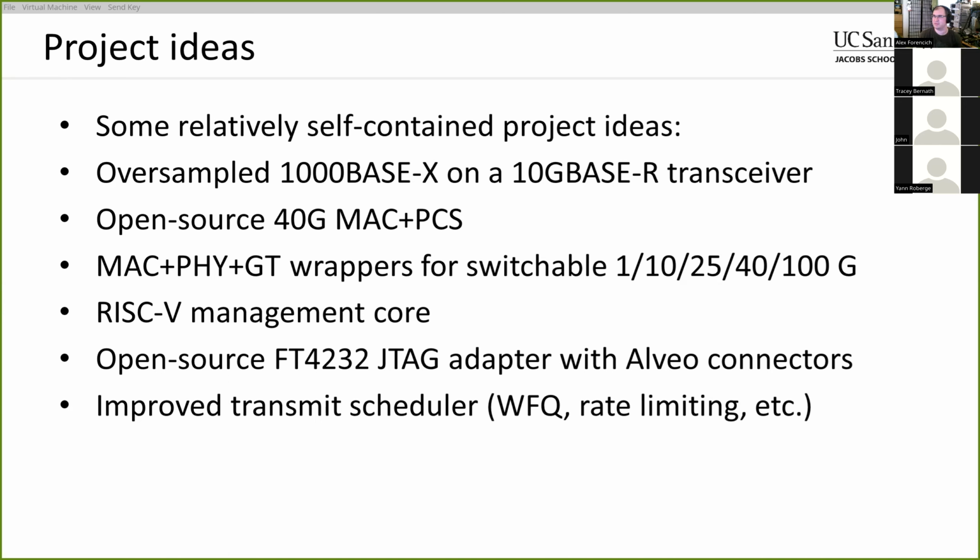Although I guess what you can always do is potentially have two copies of the firmware. One of them built into the bit stream and preloaded into internal block RAM, and then another copy of the firmware in flash, and basically a bootloader that checks to see if it's there in flash. If it is, then it'll load that one. Otherwise, it'll run with whatever's been preloaded into the block RAM. That might end up being the most flexible thing, because then you could update the firmware without having to swap out the whole FPGA configuration, just by writing that into the appropriate location of the onboard flash.